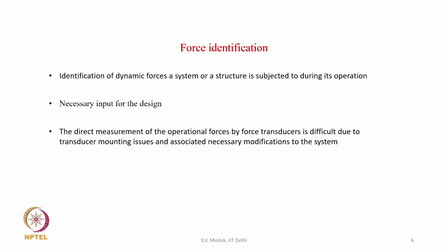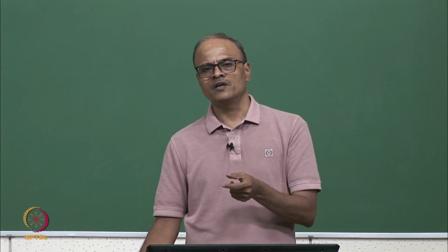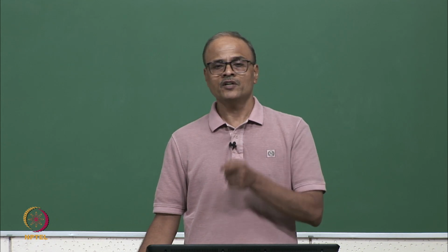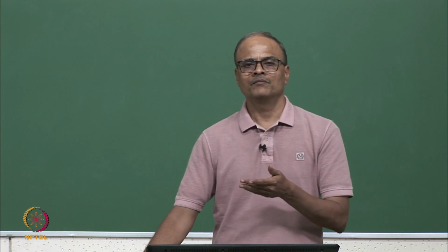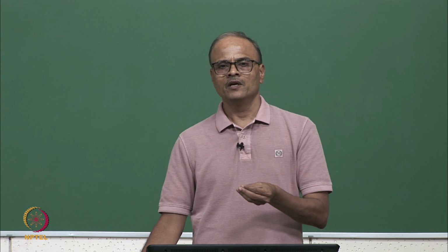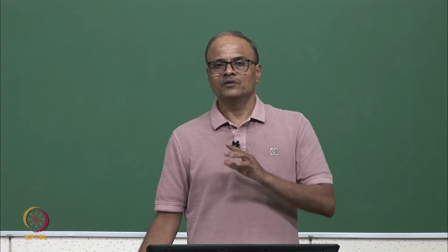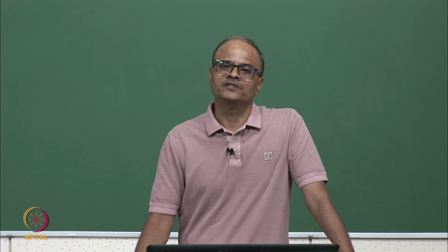If we want to measure the forces directly, then force transducers or load cells need to be mounted such that the force to be measured passes through the transducer. It has to be in the path of the force transmission. So, some arrangements and modifications may have to be made in order to mount the force transducer in the appropriate path. These are the practical difficulties in the direct measurement of these dynamic forces.